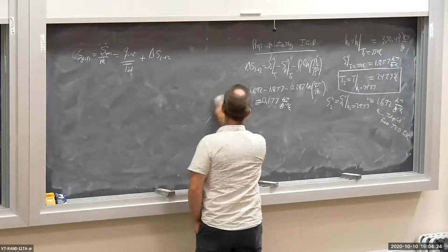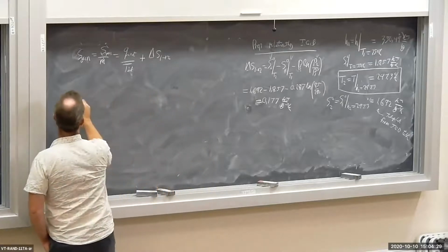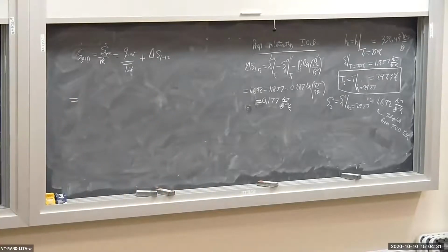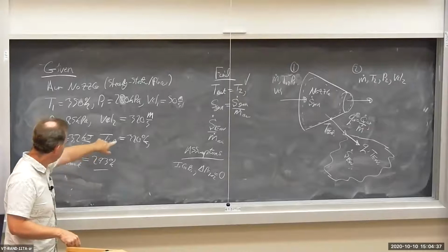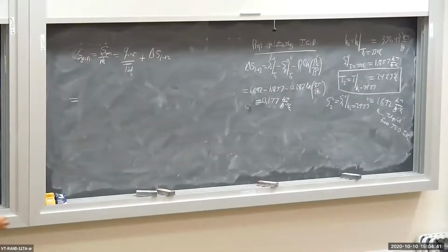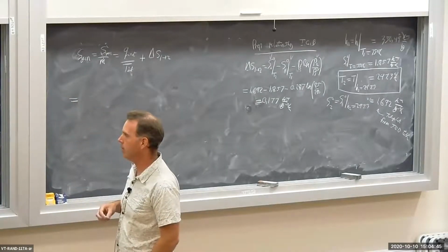Let me get rid of this, same equation. And I get Q out. Q out is 3.2 kilojoules per kilogram, and the interaction temperature is 320 degrees. That's how hot it is where the heat's being transferred at the outside of my nozzle.